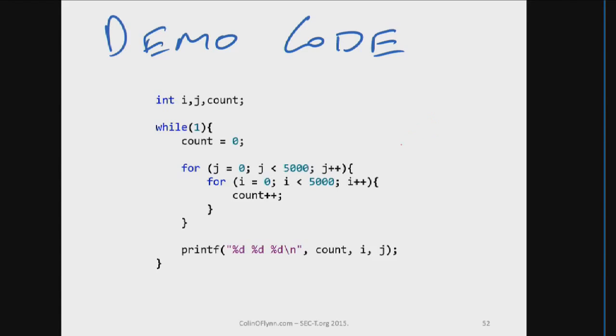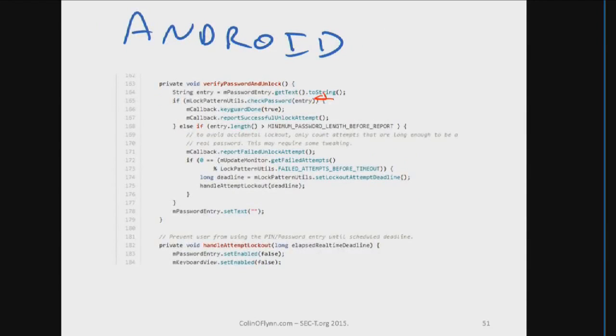So the demo code I'm running to make it easier to see for the demo purposes is I just have this for loop. So there's an inner loop and an outer loop. And the objective is simply to cause it to either break out of this loop or otherwise do this count incorrectly. What this means is that it's either skipped over an instruction or executed it incorrectly. In practice, what this means is that if you're able to get that to work, it's more or less a matter of either timing or luck to try to get it to break over specific instructions within the device.